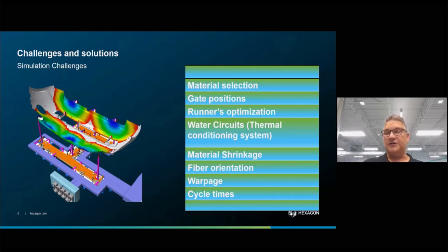There is also the injection press settings. That is a lot of variables to contend with. Fiber orientation. This is based on part geometry, runner design, gate location. Also, the fiber orientation can be different from the original part to the final part with warpage.